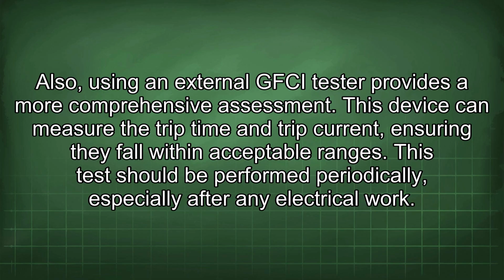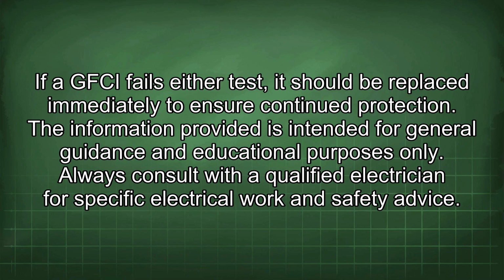Also, using an external GFCI tester provides a more comprehensive assessment. This device can measure the trip time and trip current, ensuring they fall within acceptable ranges. This test should be performed periodically, especially after any electrical work. If a GFCI fails either test, it should be replaced immediately to ensure continued protection.